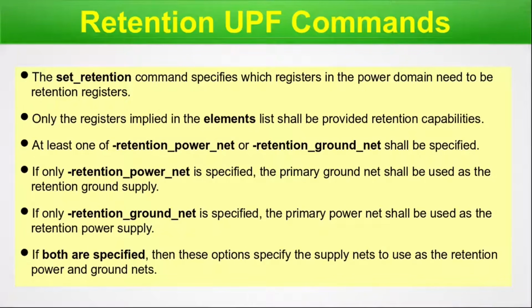So guys, it is very simple that this particular command has to specify along with it any one of the retention power net or retention ground net. Okay, so this will instantiate the retention cells or flops into your design through the UPF text. We are done with this particular slide. Let's move on.